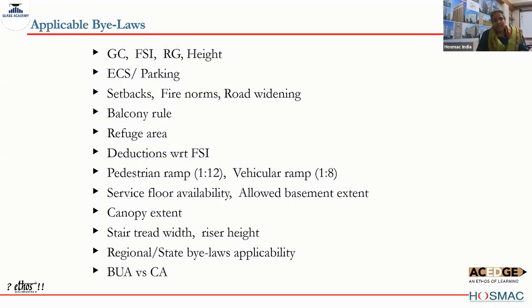So the tread width and the riser height are also specified in the NBC. A stair tread width will always be 2 meters in a public building, in a hospital building. That is a fire norm, it's a law. And the riser height in hospitals will be 150 mm. So the riser height is what determines the floor heights. Okay, so multiples of 150 mm, 300 mm, 450 mm will always give us the floor height.